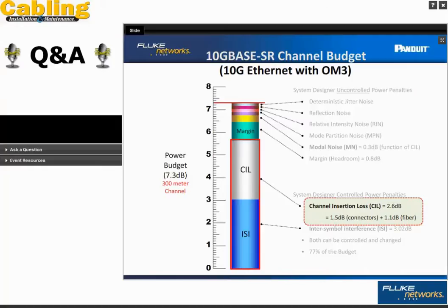Go ahead. I think we kind of answered this in the first question. Again, it's adherence to the application standard, and it's maybe not so important for 1 gig links, but for higher speed links, the application guidance is to have both a guarantee on the individual component loss of no more than 0.75 dB per connector. The reason for that is buried in the esoterica of the IEEE model. What starts to happen is you start to blow up something called modal noise.